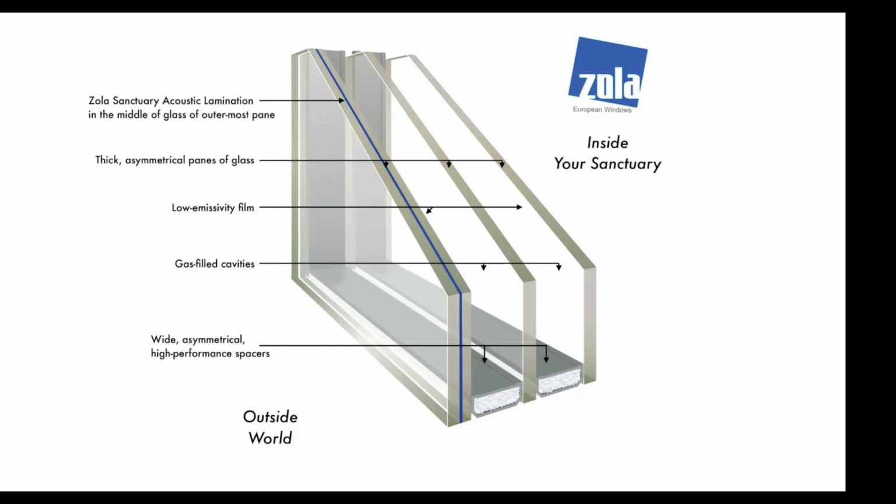For the very, very loud and the extremely large decibel ones, you might need 2 acoustic glass pieces. And do note that when you start adding acoustic glass, the performance starts to go down because you can only have a glass of a certain dimension fit into a frame, and sometimes that glass gets so huge that you can't even make it.